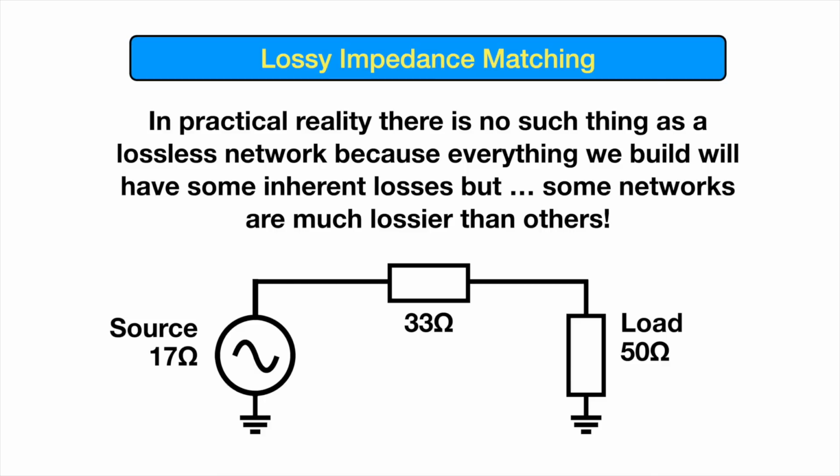You'd get a great impedance match. You'd get a very low SWR, but you would lose a truckload of your signal would fall and just heat up this resistor. So yes, it works, but there's a cost to that, and that cost is loss.